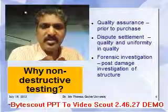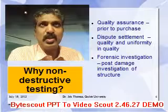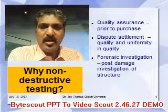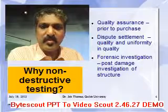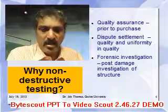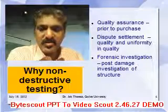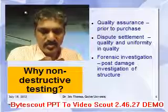One is quality assurance. Prior to purchase, if anybody wishes to do the quality assurance of the structure, then it should be done. And then dispute settlement: if a contractor claims a higher quality of concrete, then it should be done. And then forensic investigation: when a structure is damaged due to something, and if it is for material reasons or material strength reasons, it is assessed based on the non-destructive testing.